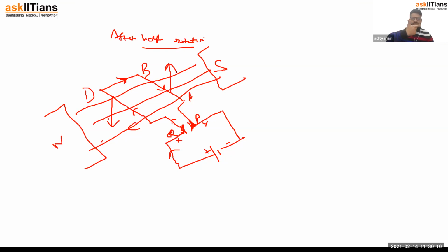If you take the direction of induced current like this towards me, and the direction of magnetic field from north to south pole, then the thumb will show the direction of magnetic force. Again, from the front view, the CD arm will have a downward force and the AB arm will have an upward force. So it will again make the coil move in the anti-clockwise direction. So after half rotation, there is anti-clockwise rotation again.